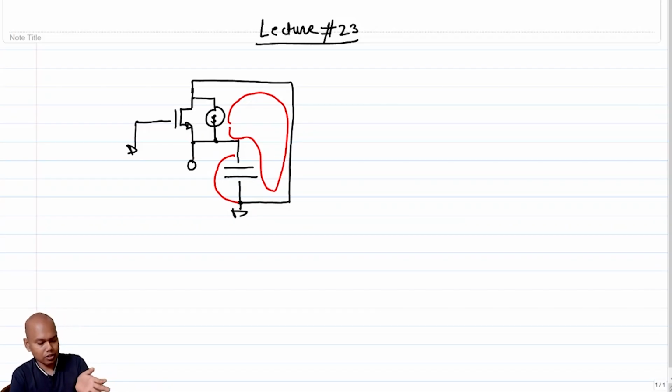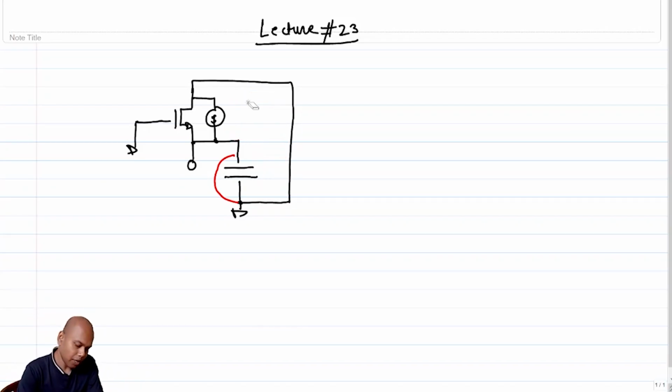So this noise current source, at least in the model that we have, even though I understand that the noise current is a part of the transistor, in this case we have taken the noise current source out and assume the transistor is ideal. So in this model, the transistor is essentially bypassed and the noise circulates in the output short, right? And hence, because the noise goes to the output, the entire noise comes out.